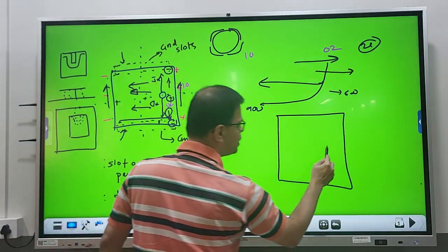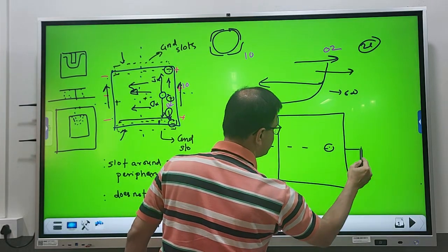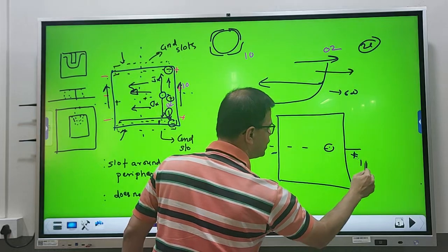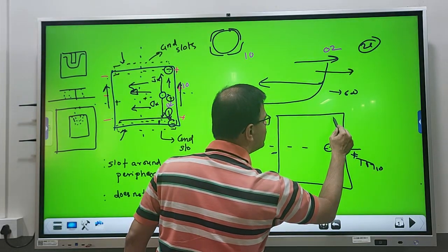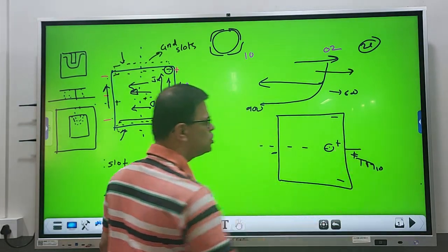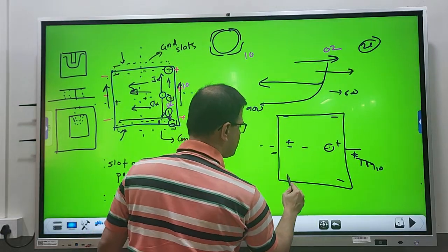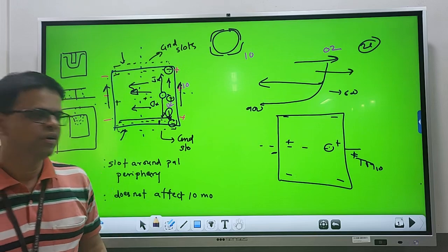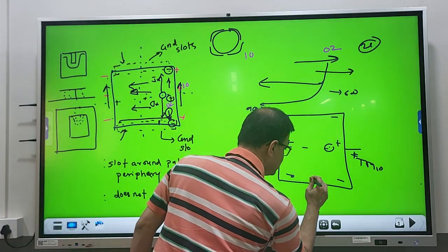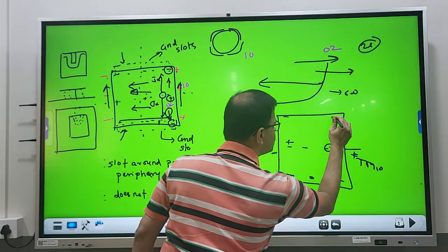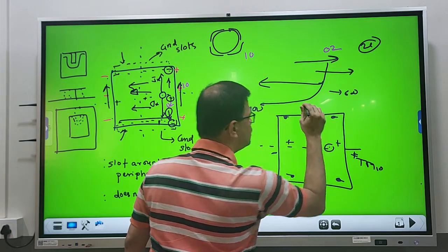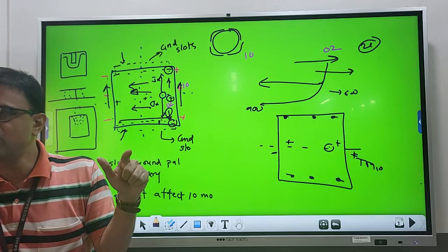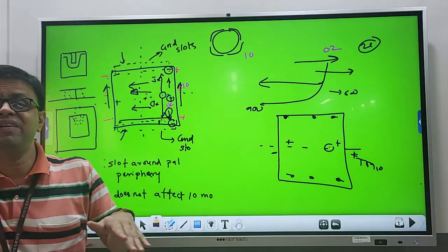See, this is your fundamental mode rectangular microstrip antenna, TM10 mode, and this is your orthogonal 02 mode distribution. Now I want to suppress the 02 mode. What people have done is put shorting posts. They have shorted these points along the patch boundaries. When you do that, the 02 mode contribution is suppressed or its frequency is increased.